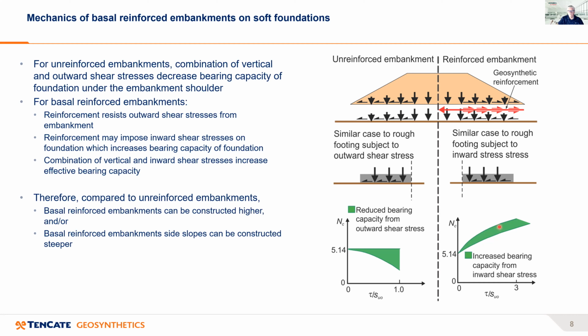So for the unreinforced embankment, the bearing capacity factor drops below 5.14, and for the reinforced embankment, the factor increases above 5.14.